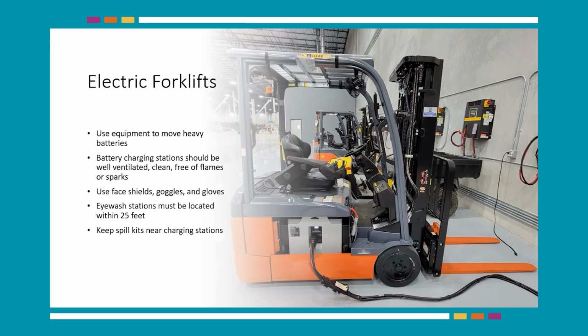Spilled electrolyte can cause chemical burns and is a slip and fall hazard, so keep spill kits near battery charging stations. Like all batteries, lead-acid batteries hold an electrical charge and have the potential to arc. Remove any metal jewelry that could conduct electricity, and be aware of any other metals in the area that may increase the risk of explosion.